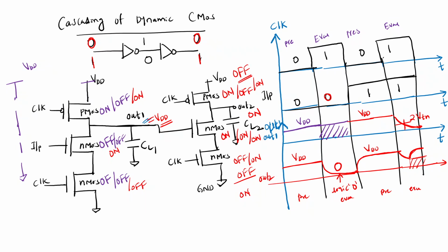So only at half clock cycle you are getting this. Whereas in static CMOS, you are giving 1, you are getting 1 only, but here the capacitor is discharging, after that it is charging. So here I can say that output is not VDD, or output is not ground.